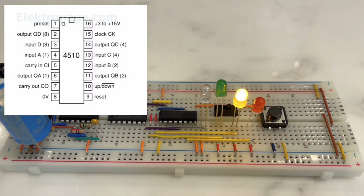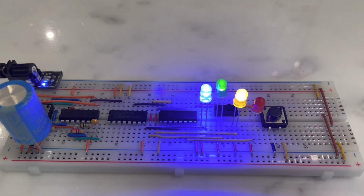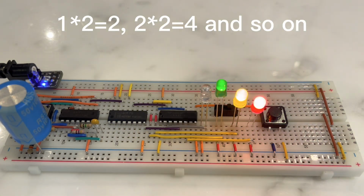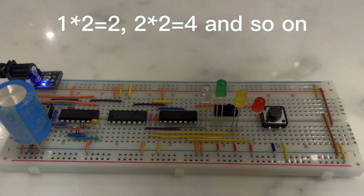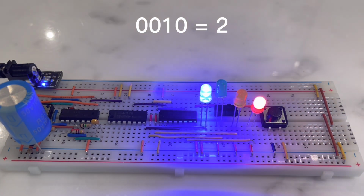The 4510 adds a bunch of new things to its pin configurations like the up-down pin and the reset pin. What this circuit is doing right here is counting in binary, where each of the LEDs represents a different value. For every spot you move in binary, you multiply by 2, starting at 1. So 0001 would be 1, and 0010 would be 2.